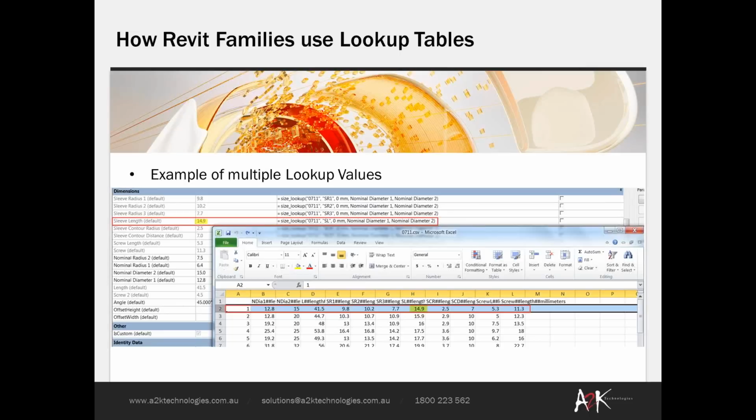So you can do it either way in terms of finding the name of the lookup table itself. Just keep that in mind. The reason why it's sometimes better to do it as the lookup table text name is because if that name changes, you only have to change it in one spot, and all of your formulas will change to suit, because they're all just referencing that lookup table name, rather than having to go into each formula and change 0711 to a different name if that CSV file gets renamed.